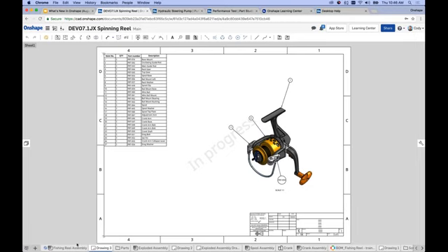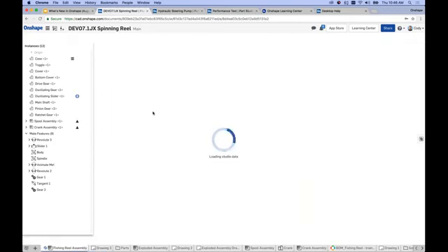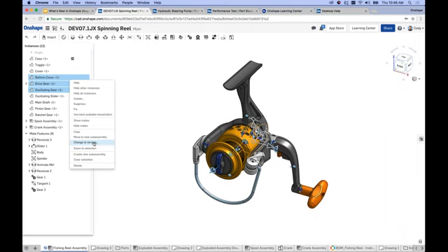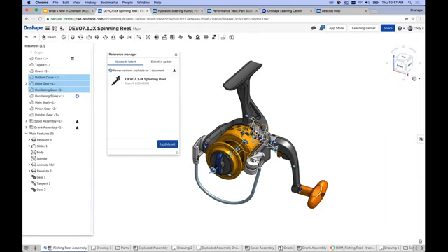The other thing I would suggest is, keep in mind, this is not just for the drawing. I can also change to version on parts or subassemblies within the top level. So let's say that I've inserted a number of parts and then I need to swap them for Rev A or Rev B. I don't want them linked to the active workspace anymore. I could right click, change to version, choose the revision that I want, and you can see I have choices, right? So just depends on what it is that I want to bring over. If I have multiple revisions, I will have multiple revisions to choose from to bring in.